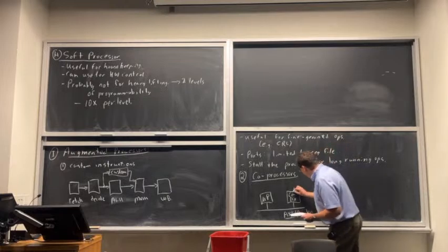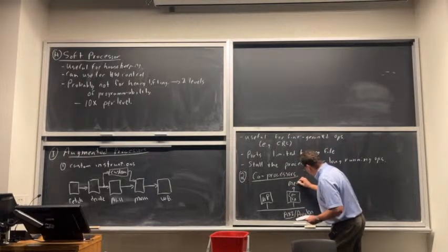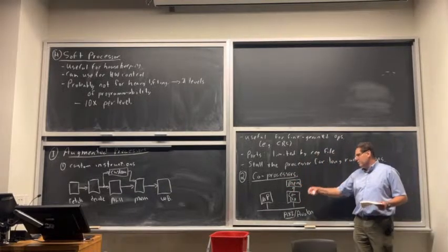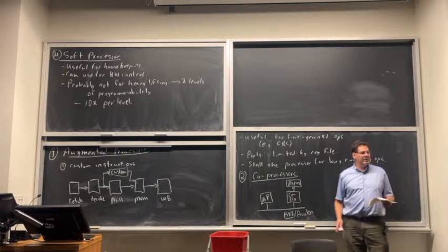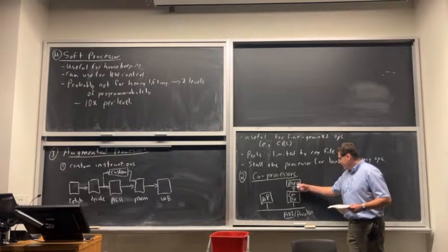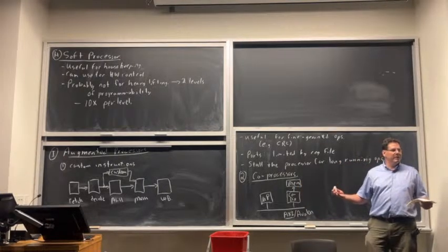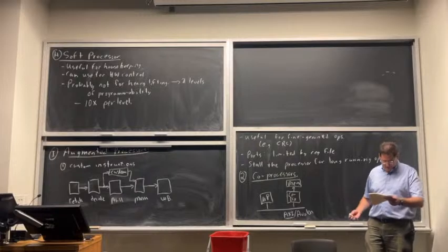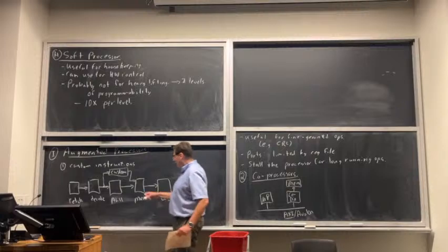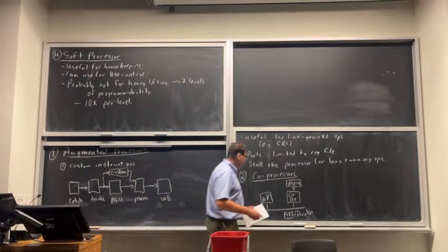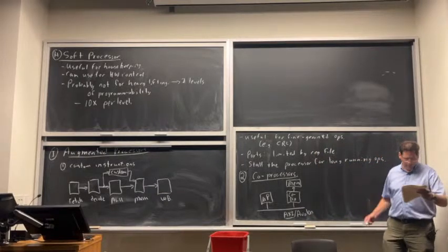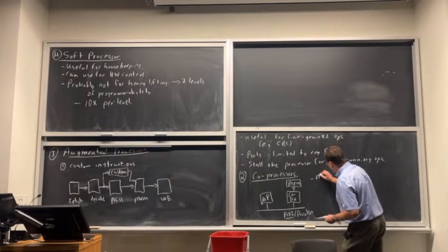But we can do things now like directly connect this processor to memory. Okay, so this could be a bunch of on-chip memory on the FPGA. It could even be off-chip memory. We could hook it into a DDR controller so we can get an off-chip memory. So what this does is, well, we have a lot more flexibility. So it's not as closely tied together. There's higher latency between them. But we've broken this limitation of we're just getting a couple of operands every cycle. We can hook this coprocessor up to on-chip memory, off-chip memory, both, whatever we want. It's our choice. So we get more memory bandwidth.